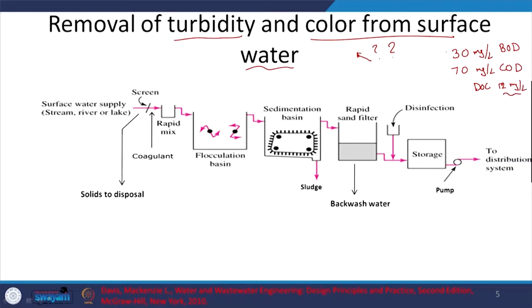So it's almost, not almost, it's under the category of sewage, let's say. So that's why they were using MBBR, moving bed biofilm reactor based plant, to treat the water and then supply it for drinking water. So that's the kind of unique process that people have to employ based on the kind of water that they take. But that's a unique case.